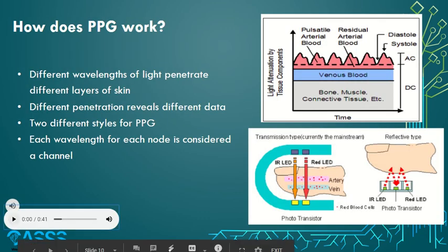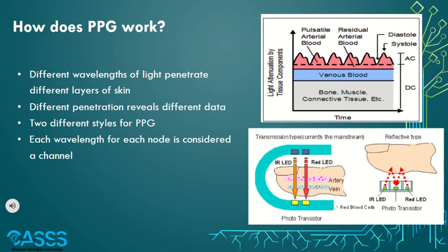Typically, PPGs operate two types of LEDs, IR and red. The light absorption of IR and red light is different between hemoglobin and oxyhemoglobin, which are blood molecules that are either oxygenated or not. With these changes of light absorption, we can compute metrics like heart rate, saturated oxygen, and blood volume. There are two main types of PPG sensors, transmissive and reflectance. However, we chose reflectance type PPGs so the user can easily wear the device. When transmitting data, a channel represents a single PPG sensor.